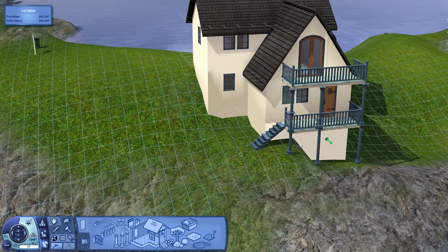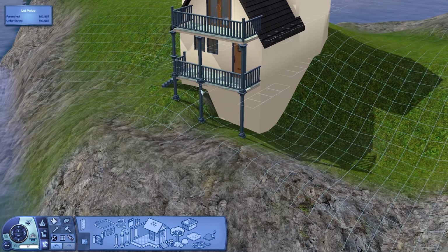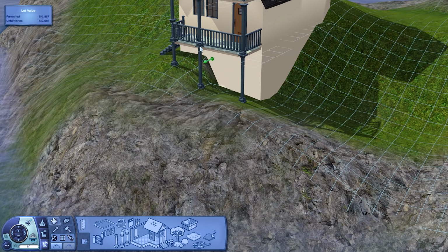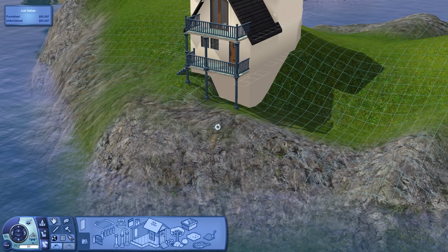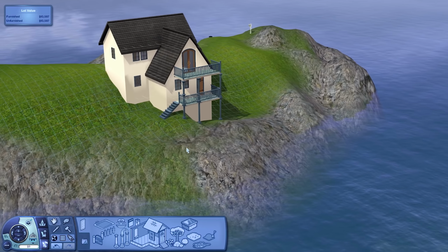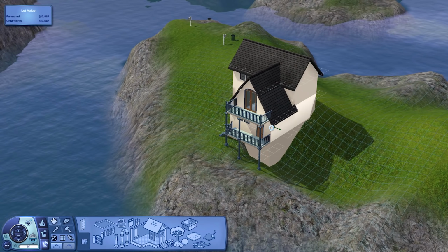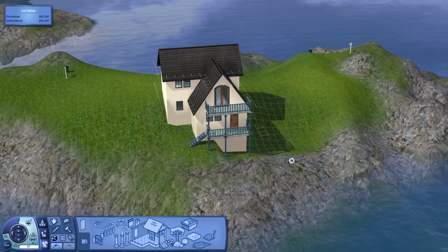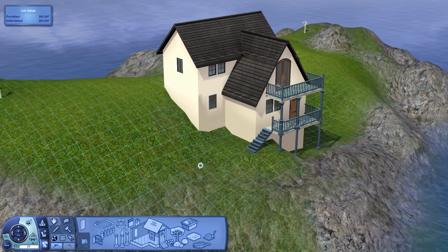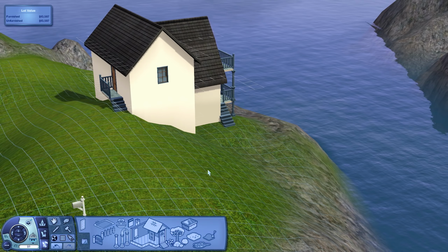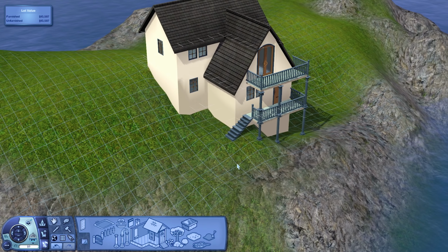Also, instead of putting a giant foundation block here where I have this huge height difference, I used these columns and placed them in using move objects, which is another cheat. So there are ways of integrating a house into the terrain that look pretty cool. Anyway, I hope this video was helpful and that now you can start building houses into the terrain in more interesting ways. It's not really that difficult just as long as you use constrained floor elevation.